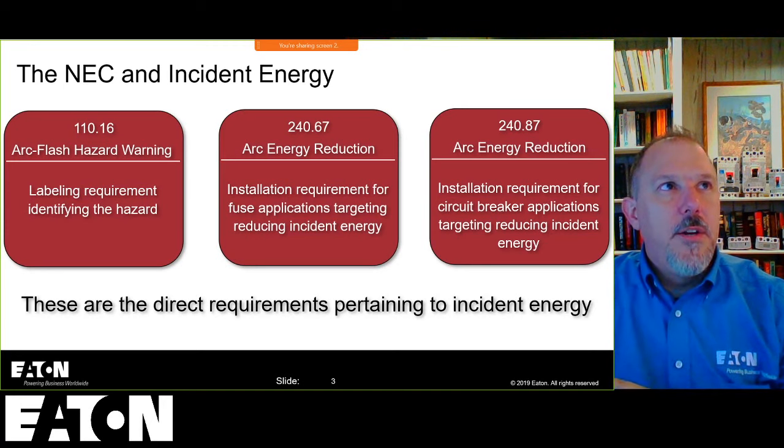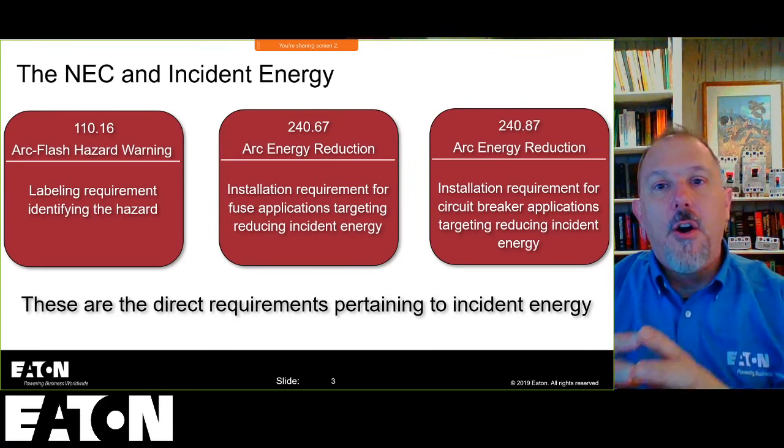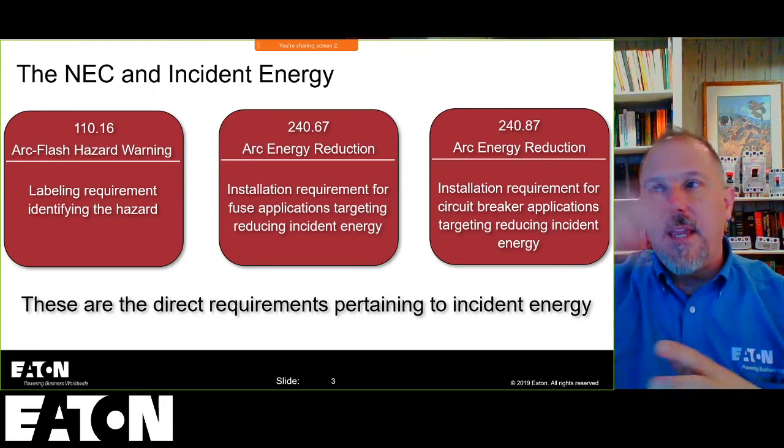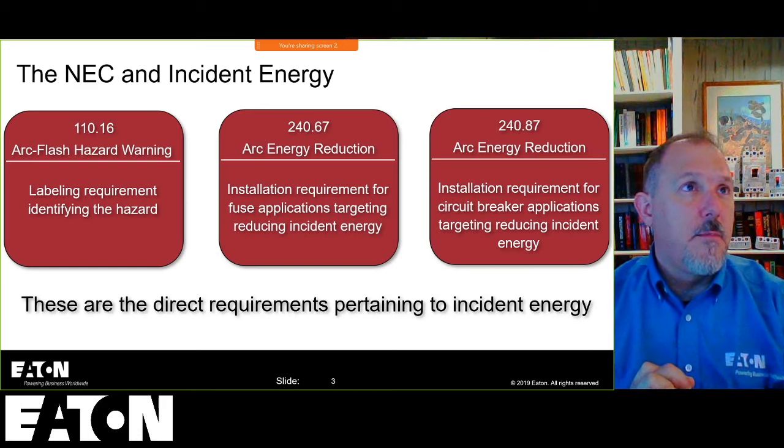And Kevin Ryan noted that's why you have to use multiple scenarios and take the worst incident energy. Absolutely right. And what we're going to talk about are all of the different types of scenarios where you get the high fault currents and the low fault currents. You've got to think about what those scenarios are for each of your power distribution systems.